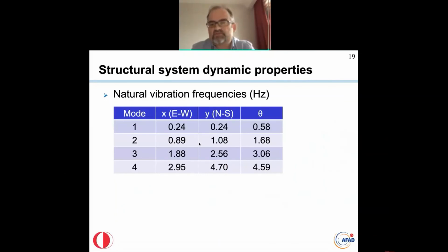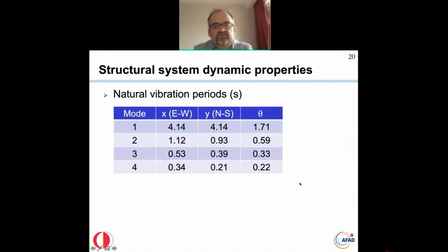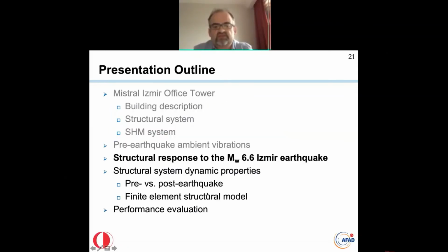Well, as structural engineers, we are more comfortable using periods, therefore let's switch to periods. So the fundamental period along both axes is 4.1 seconds, and the second mode periods are around 1 second. Well, now the response to the earthquake.